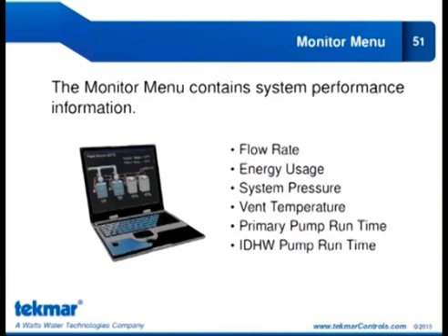So if you choose to, say, control your common vent, you can program a vent maximum. So the idea there is if that vent temperature reaches that vent max, let's just say you program, say, 350 degrees Fahrenheit, and it reaches that, it'll turn off the plant.